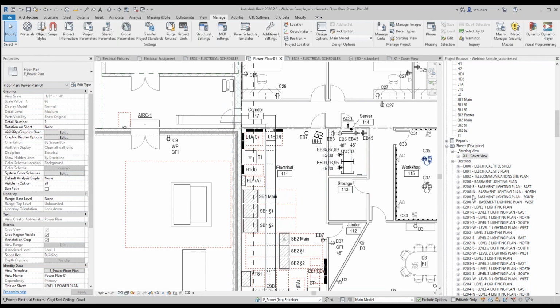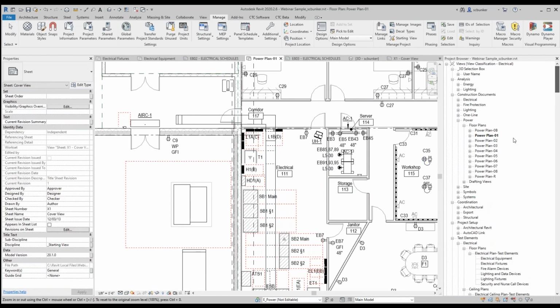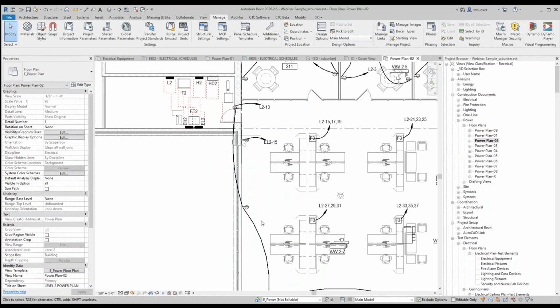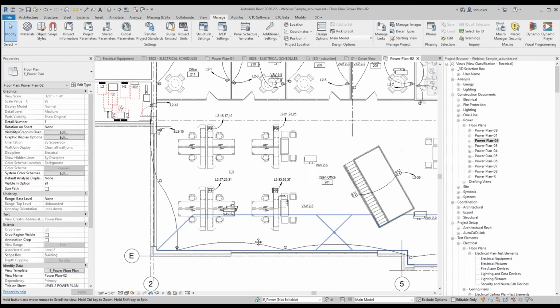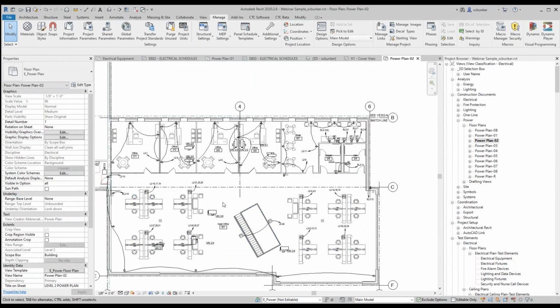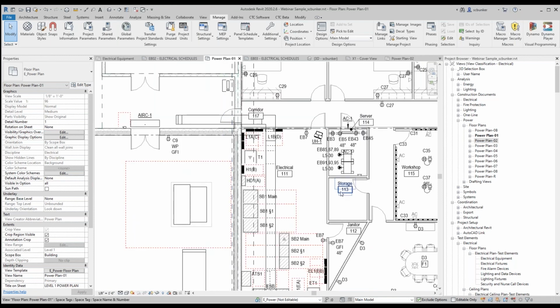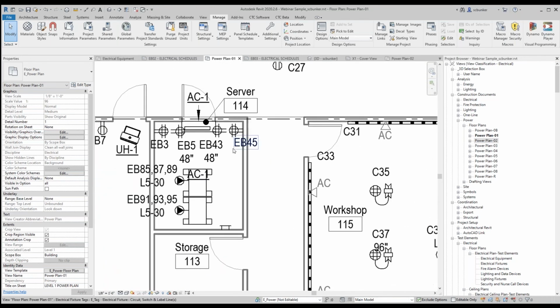I think it was circuiting. Again, we want to do whatever anyone wants to do, okay? As much as reasonable, we want to accommodate your workflow. So if your workflow is using arc wires, you can use arc wires, okay? We've got it here. So all of level 2 is circuited using arc wires. But in Revit, it's actually faster to use tags. And that's what we've done here.